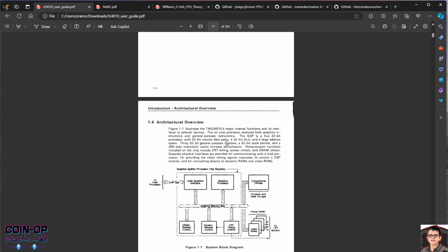And so I needed to create a microcode engine for this CPU because I built it by using regular logical elements at first, and it was too large to fit. So I created a microcode engine to do this. So there's all sorts of design aspects you have to go through when you take a look at different chips and use the manual and data sheets to discern that.